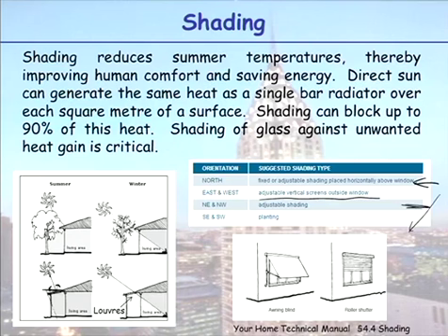Has anyone got their bedroom on the east or the west, or their television room, and the sun comes shining in on you and you can't see anything and you've got to close your Venetian blinds? So on the north side, horizontal shading is good enough. On the east and west side, you need vertical or adjustable shading.